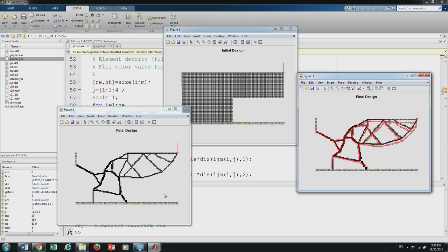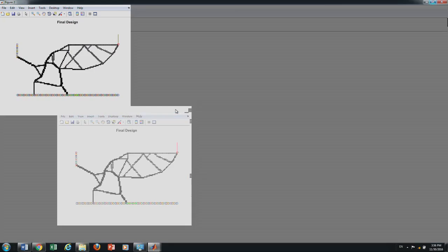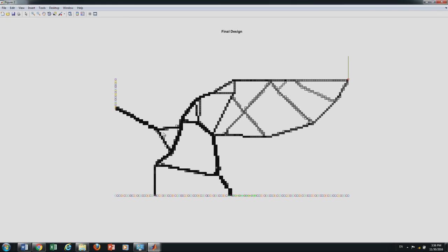If we go a little finer, some of these things will go away, the gray ones will go away, or it will be a weak mesh there. We have a beam, a beam, a beam, and we can actually put beam segments. Somewhere here it still wants to go for a hinge, we will talk about that. There are two elements diagonally connecting here, it wants a hinge here, a flexural joint. The rest of it is there, and the topology has not changed.